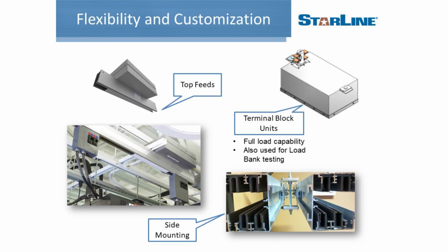So once again, thinking about the modular approach, the flexibility and the customization aspect is definitely something else that we want to keep into consideration here. Having other ways to feed the bus, so top feeds, bottom feeds, terminal blocks utilized to fully load bank test the bus before it's turned up, and you bring in your critical loads. Those are all necessary piece parts to the puzzle.